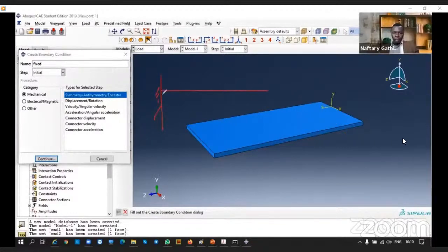And then this is our plate there. I'm showing the thickness direction and then a load pulling there. So for you to understand clearly, usually the plate will be maybe in this direction, and then a load is applied here. So this is fixed. This is why I'm using this option, encastre or fixed end.